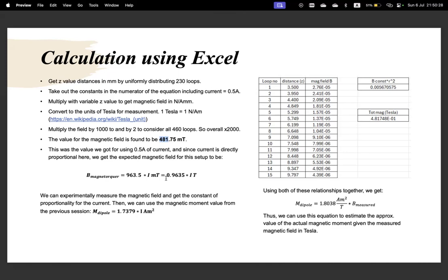So in our discussions with customers, we don't actually say that the magnetic field we generate is this many millitesla. No, we say we're going to generate for you 0.4 amp square meters, for example, okay? Because that moment can be more easily used to choose a magnetorquer that is sufficient for their system.